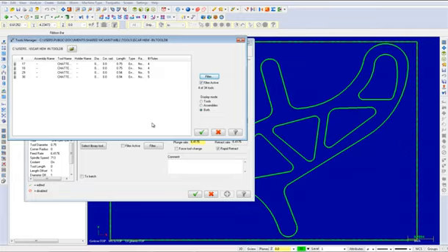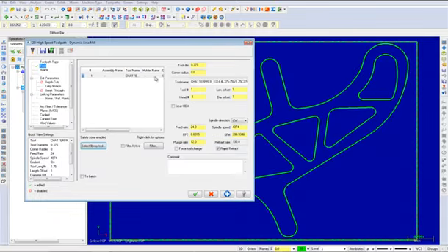Select the first chatter-free 3/8 end mill in the Tool Selection page. Now choose the OK button to continue. Your tool will appear as shown. Enable ISCAR HEM as shown. Now change the HEM factor to 1.25.